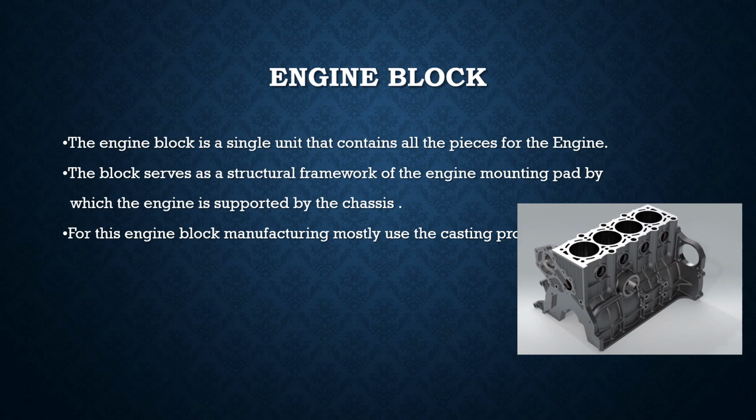Engine block is a main part in an engine, which contains 20 to 25% of the weight of the engine. The material used for the engine requires more strength with low weight. The design of the engine block depends upon increasing the power, durability, wear resistance, and efficiency of the engine. The requirements of the engine block include wear resistance, long-lasting life, maintenance, and withstanding the pressure created when combustion takes place.